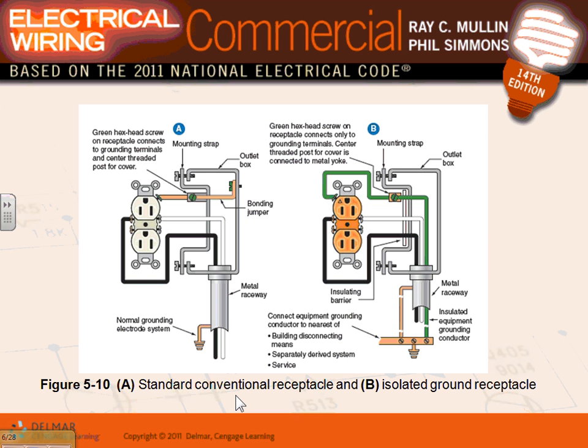So, a standard conventional receptacle and an isolated ground receptacle. This one here is tied all together to the frame. This one is completely isolated, going all the way back. So in a box like this, then you're going to have two grounds. One equipment grounding conductor to ground the yoke, the ears, and the other equipment grounding conductor is for the grounding slot, which is that little screw here. You have to have two.